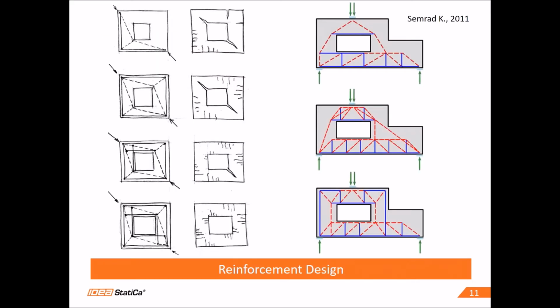As I spoke about the strut and tie method, the usual disadvantage is that for the same model, like in this case a wall with an opening, you need to work with many models to capture the real failure of some specific detail, right?